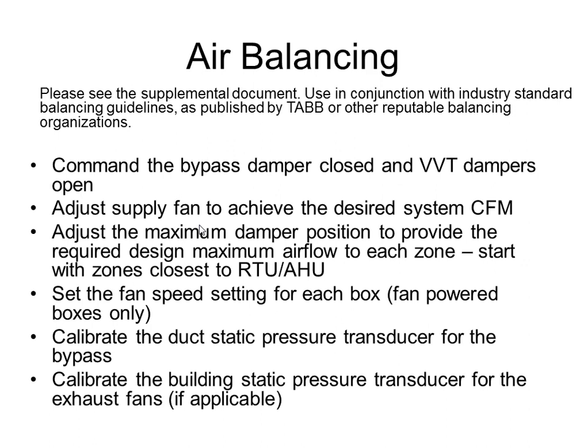If you don't have the system balanced properly, you might not get the proper CFM out of zones, and some zones will always be calling because they don't have the proper airflow coming out of them. You can have a bypass damper that has a static pressure set point that is not the total static pressure that's in the duct, or that's not supposed to be maintaining, and you could be bypassing too much air. There's a number of situations that you can run into without having an air balancer here.